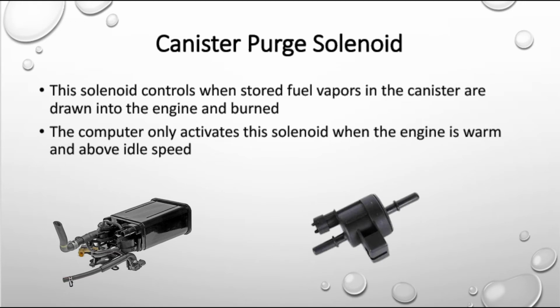Canister purge solenoid. This solenoid controls when stored fuel vapors in the canister are drawn into the engine and burned. The computer only activates this solenoid when the engine is warm and above idle speed.